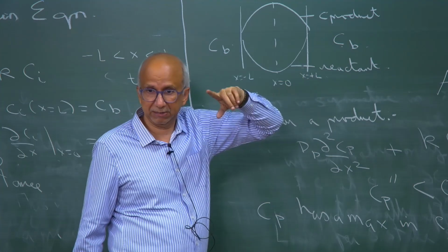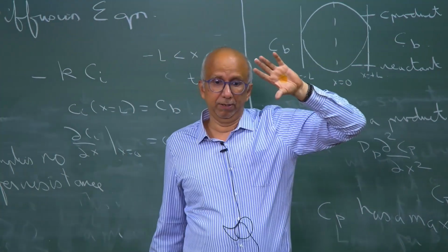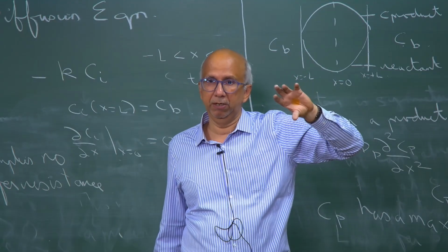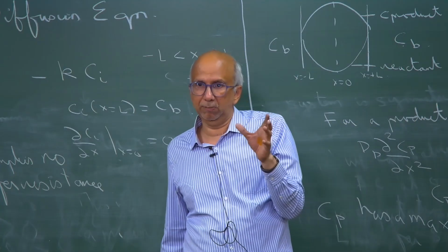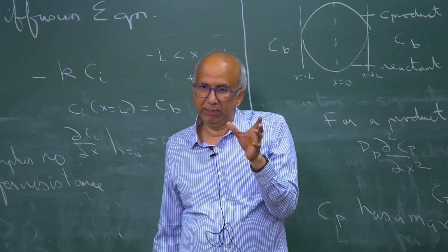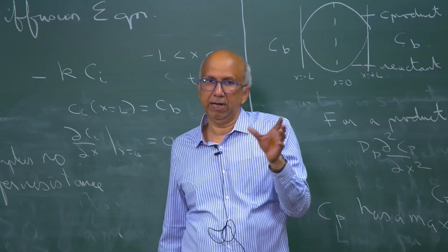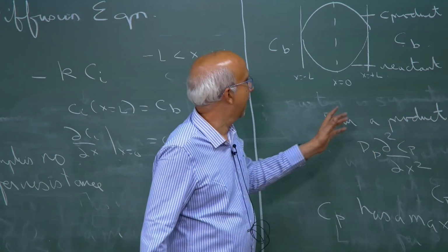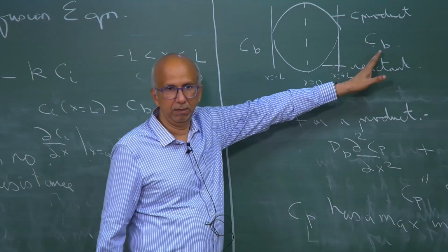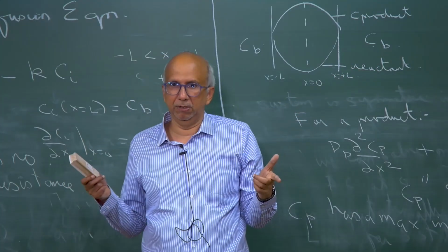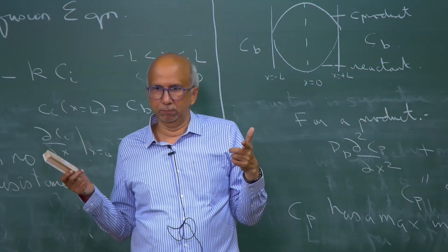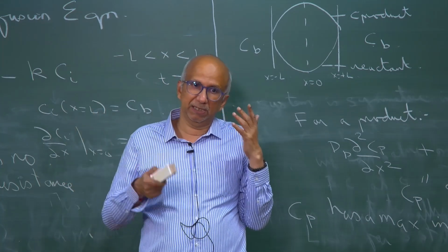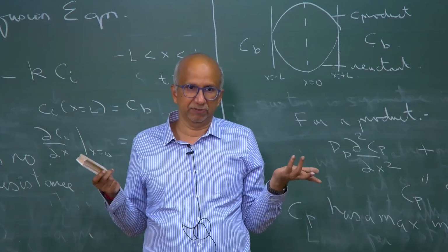In the last class, when we did the heat transfer problem, we were talking about conduction in the sphere and the heat transfer, so we were only talking about the balance between the internal and external heat transfer resistance. We spoke about Biot number being very high, very low. The comparison was between internal and external heat transfer resistances.